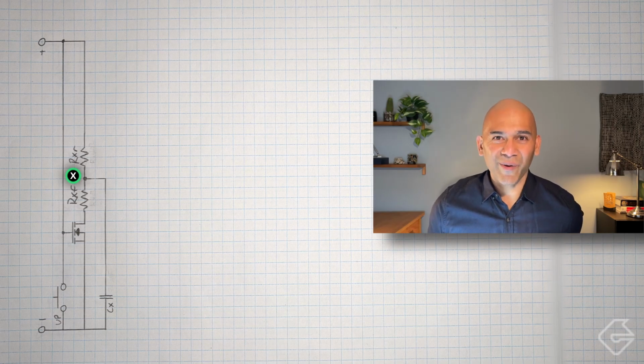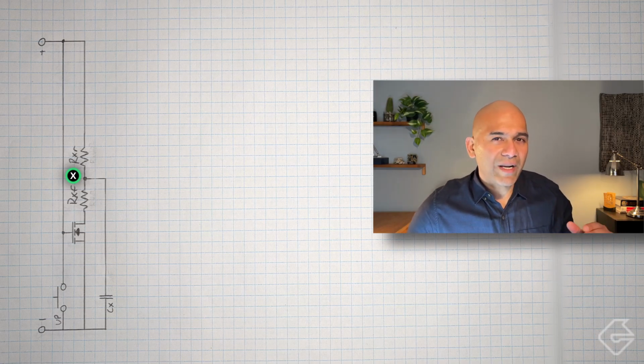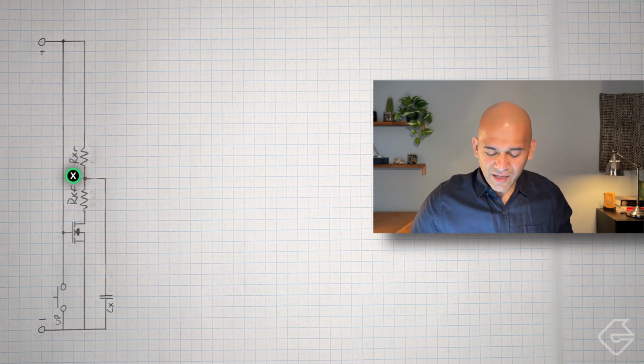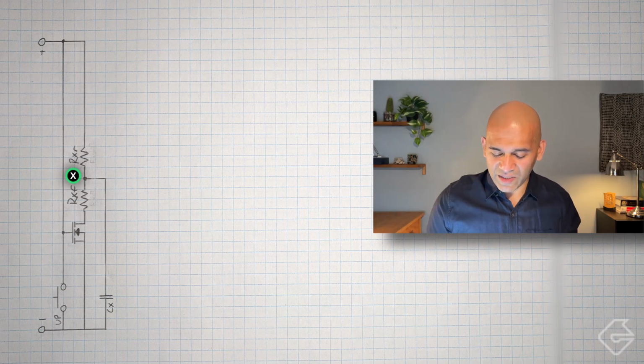This works very well. Slight adjustment is needed though. This is a physical switch, and generally we want to keep the current flowing through switches at a bare minimum because there are contacts rubbing, connecting and disconnecting. So there could be sparking going on here if the current is too high. And right now we don't have anything to limit the current going through this switch. That's very bad indeed.